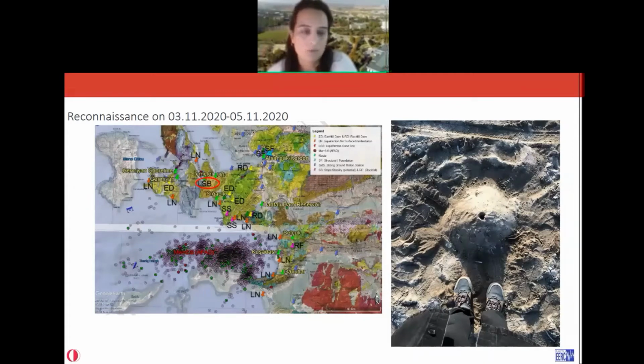And the site is located about 50 kilometers away from the epicenter, and the PGA levels are relatively lower, around 0.05 to 0.1 G. So that might probably be the lowest PGA level that can trigger a surface manifestation of liquefaction. Another thing that we have learned about the site is that there are some hot springs in this region, and that might also contribute to the liquefaction.